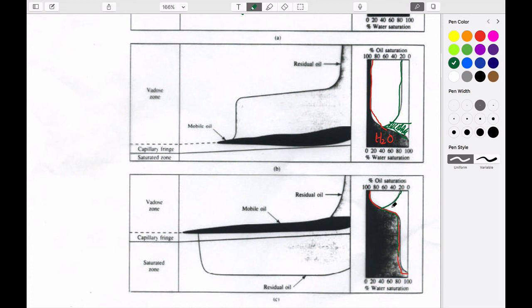So what we have now is a lens which is at relatively high saturation, which is sitting here and goes down to some depth, I suppose. But here we have this smeared zone. And this smeared zone is really just the same as the zone that's above it. So we have a much larger volume here, which is at relatively low saturation. Maybe the saturation of the NAPL is, well, you can see from here, it's 20%. And now, when water gets carried through here by the action of groundwater, due to the head gradient, it will dissolve this stuff and travel it downstream.